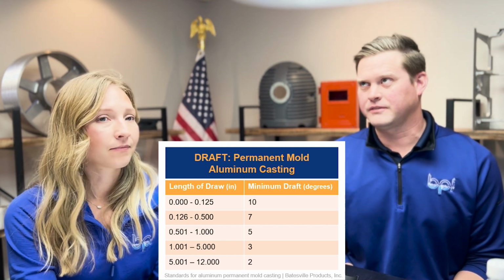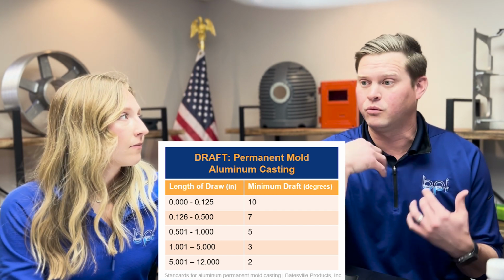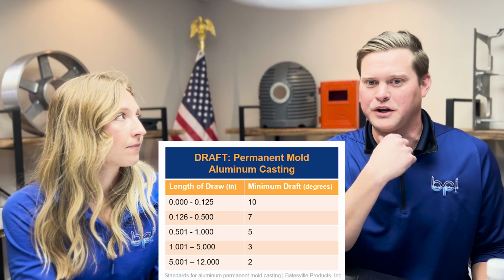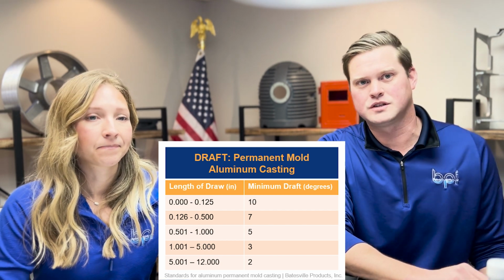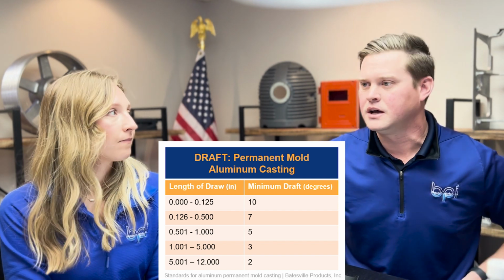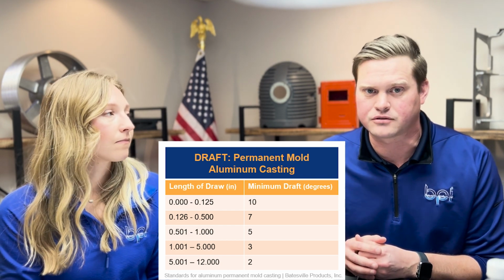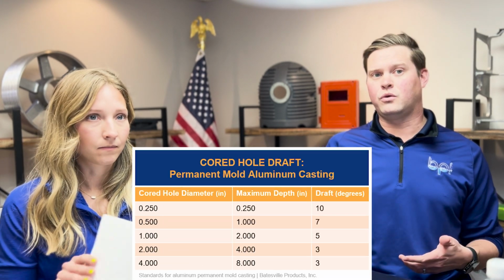Yeah. Again, draft is important. If you think about what Rachel was talking about, we're casting in permanent mold, we're casting into steel molds. So you're removing a metal from a metal. The best way to do that, as Rachel stated, is the more draft you get, the better. What's listed on the right side of the screen there are really minimum draft requirements. But there's always the option afterwards to machine away in critical areas that need less draft if that's a requirement.